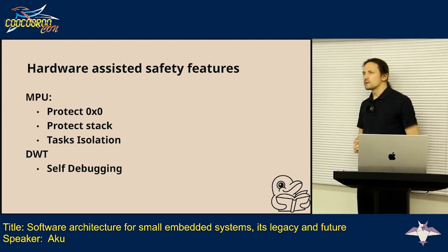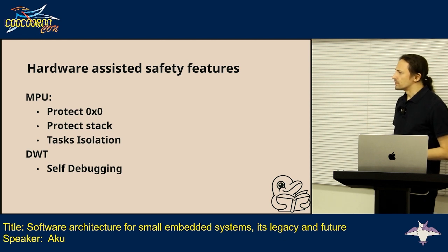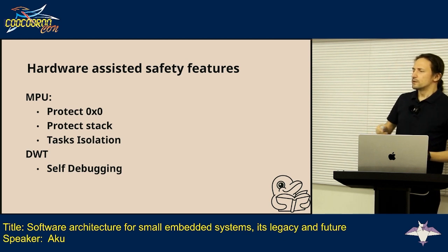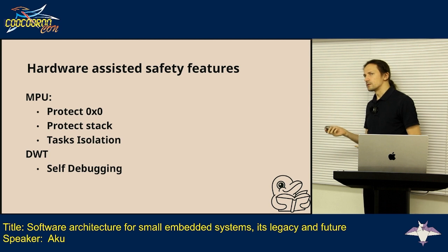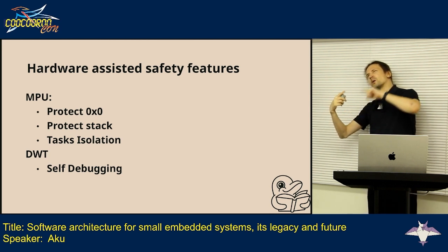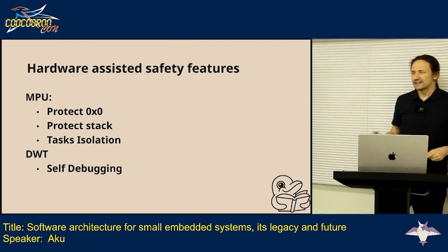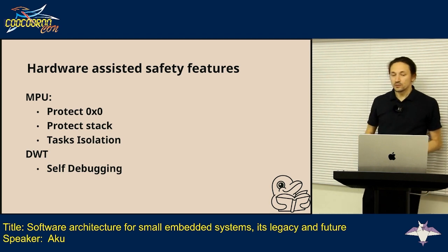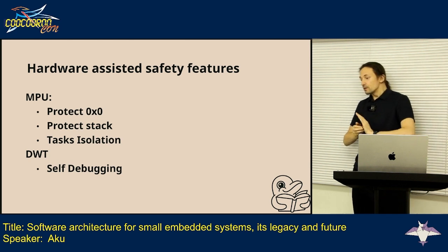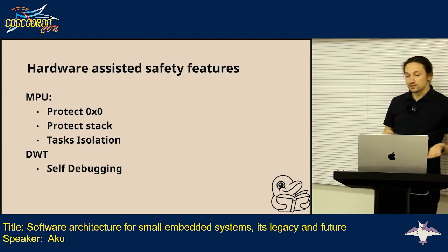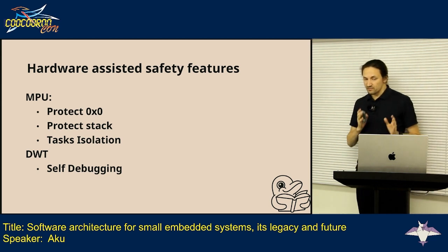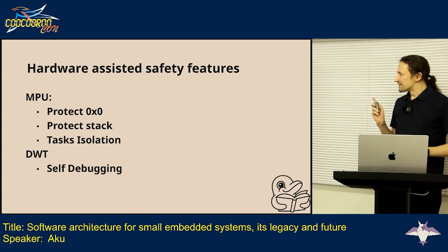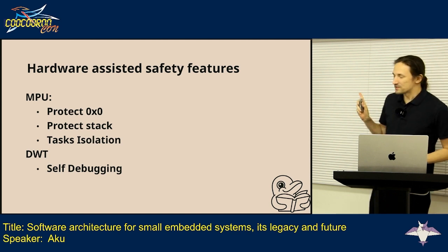Obviously, there are some caveats, like the one that I mentioned about interrupts on ARM cores. They're not delivered immediately. You'll have to wait at least 20 cycles, so you'll have to go back in your instruction stack to find what exactly happened. But still much better than not having this subsystem. Other MCUs, not only ARM cores, have those debug capabilities, but you will be able to find them in the specific instruction set and architecture documentation.